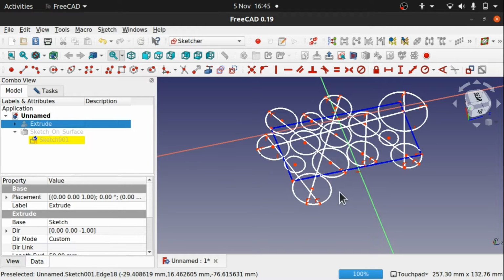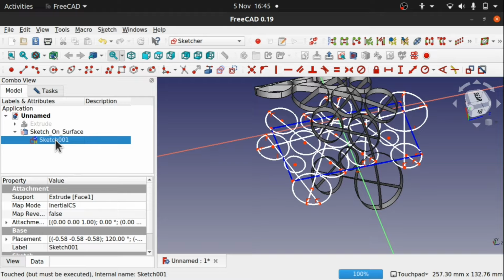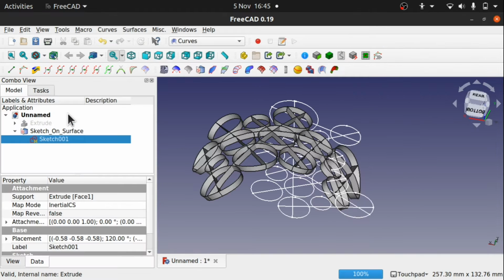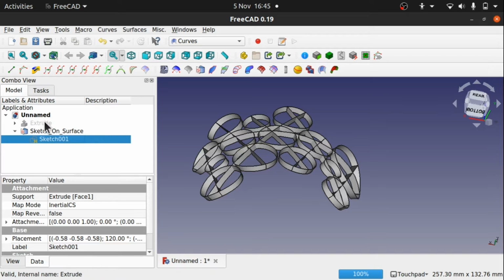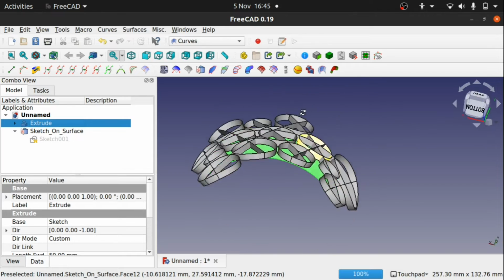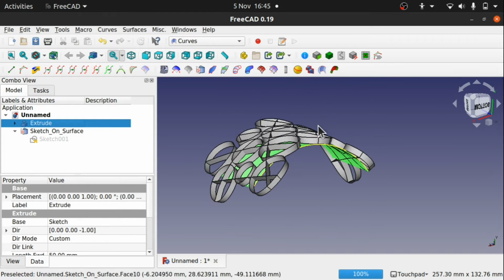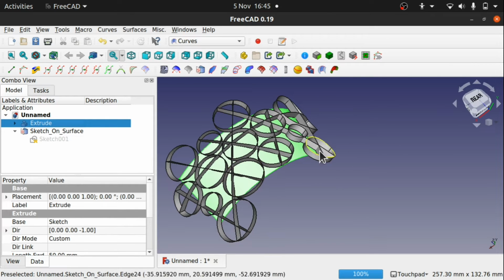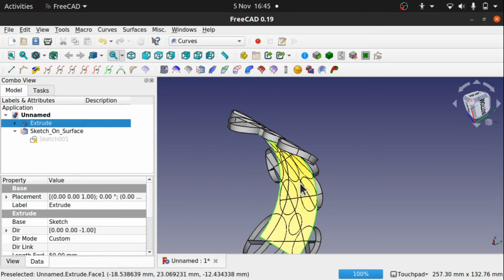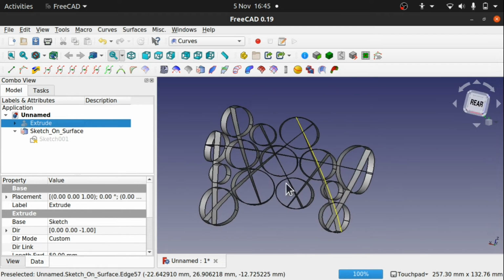For instance, we have this simple sketch here, and what I've done is created a curved surface from that sketch. We go back and curve this around an extrude. So we just use a simple surface in there to extrude these out of. We could use additional cuts and unions to actually get the shape under here from the Part workbench, but we're concentrating on creating curves and the problems that we can get with this tool when we go through the process, and how to overcome those.